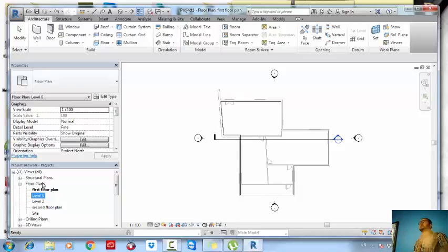If I am drawing a window, is it a casement window or a sliding window? The window is the family, the generic family. Fine. The type is sliding or casement. So first you select the family, window, then you decide the type, then you use it in your project. After that you will have all the things that you need, all the information, plans, sections, elevations, schedules, whatsoever. Fine. Let's practice. Go ahead, guys.